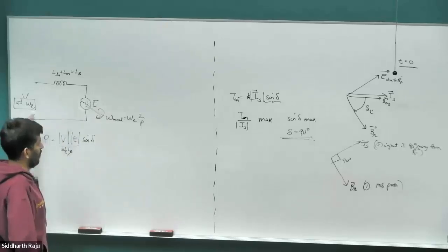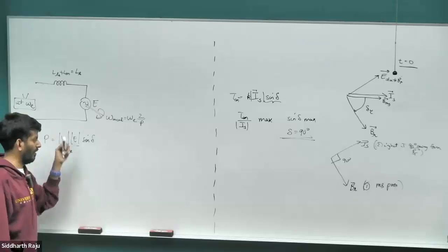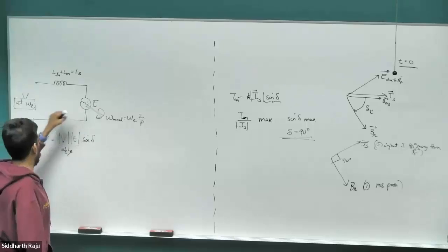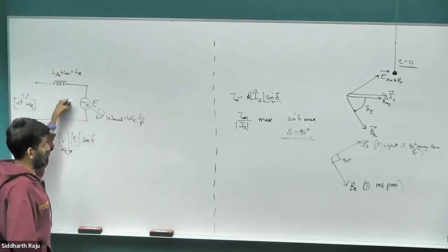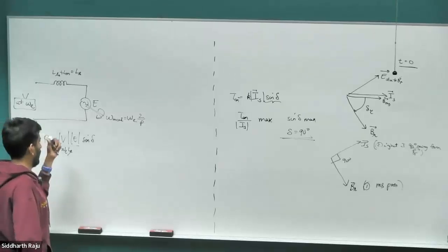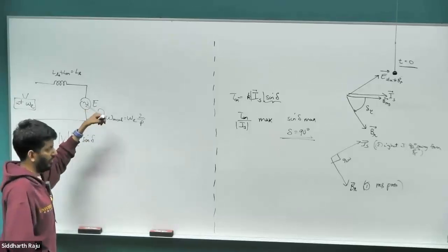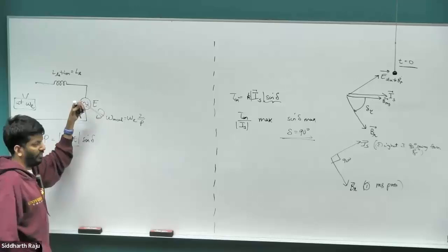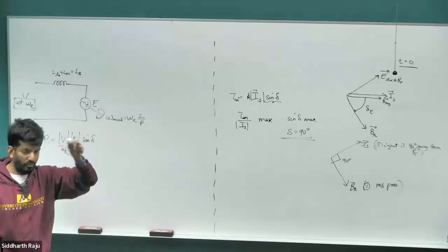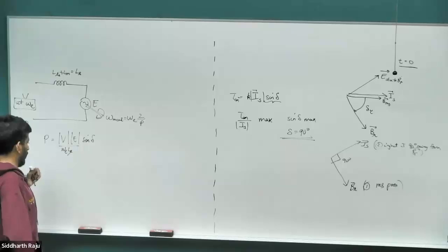In an AC network, if you have two different frequencies, you can never reach steady state, unless they are multiples of one another, in which case you can still reach some kind of quasi-steady state. But if they are non-multiples, which would be the likely case if there is random speed, then there can be no steady state situation at all. So for that requirement, as well as the way the motor operates, as we saw last time, if the rotor is rotating at some 65 radians per second, the electrical frequency for a 4-pole case would be double that, because every half rotation, the stator coil sees one full sweep of north to south pole. So it rotates at twice the speed at which the mechanical speed will rotate for a 4-pole motor.